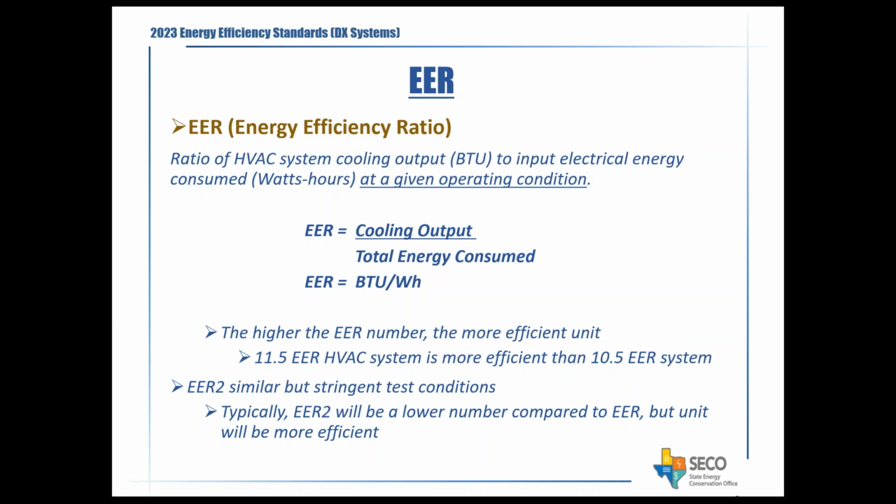So the energy efficiency ratio, or the EER, is the value showing the efficiency of a system at peak load. That is important. So they look at the peak load and what is the efficiency of that system. EER is generally calculated using 95-degree ambient conditions and an inside or mixed air temperature of close to 80 with a relative humidity in the space of 50. So they define these conditions over there, in which these things are tested. So that's the main difference between SEER and EER.